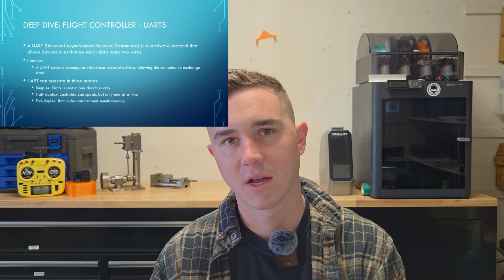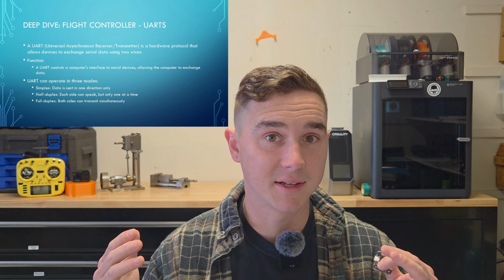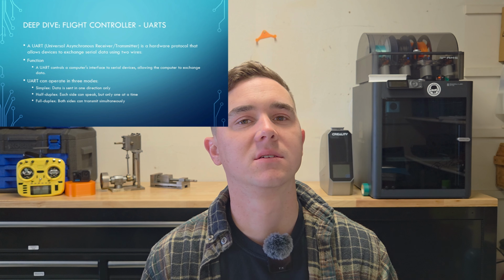There's some things to consider with UART. Generally speaking, a UART has a TX and an RX. You have simplex, which means data can only be sent in one direction only, either from the flight controller or to the flight controller. You have half duplex, which means it can send and receive, but it can't do it at the same time. And you have full duplex, which means it can send and receive at the same time.